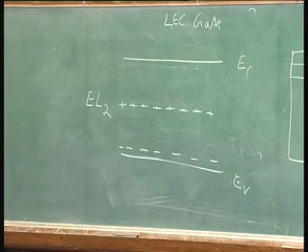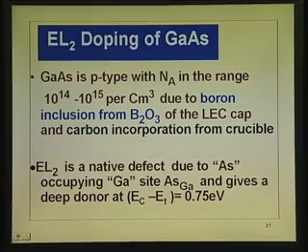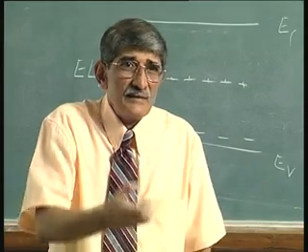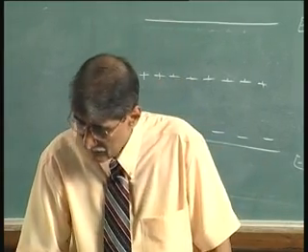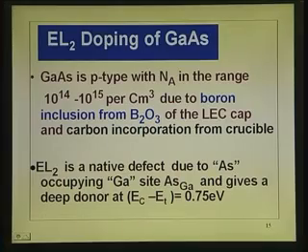This is the result of the defect, which you normally may not like, but you like it here. You do not have to worry about this particular defect moving into the next layer. It is not like the impurity which will run. So that does not move, unless you go to the liquid melting point of the gallium arsenide.